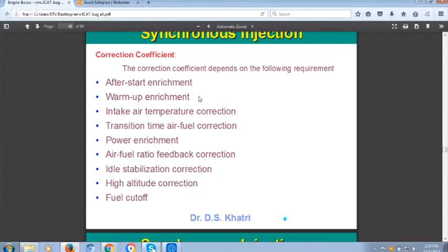Normally, an engine takes 5 to 6 minutes to warm up. Now, my purpose is how to reduce the warm up period. So this we can change, and there are two ways to do this. Number one, I make high idle. Engine speed I increase in the beginning, maybe 1800, and then as it warms up, I slowly reduce it. And when the engine is fully warm, it may be 900 or 800.